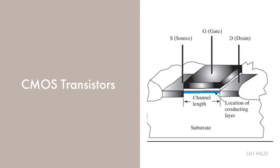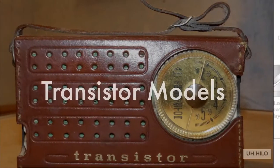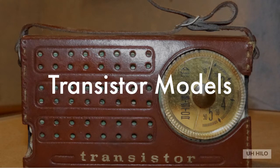On the other hand, if the gate-to-source voltage is less than the threshold voltage, the channel will be absent, lacking significant current flow. Under this condition, the transistor is said to be off. Because of the on-off dichotomy, a switch-like behavior is a good first-order model for an MOS transistor. The behavior of the MOS transistor model depends on the transistor type.